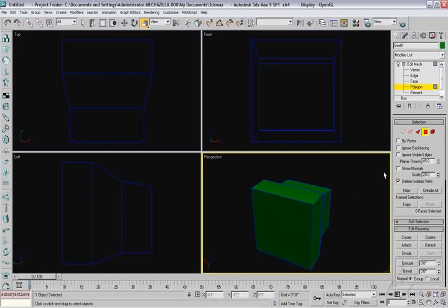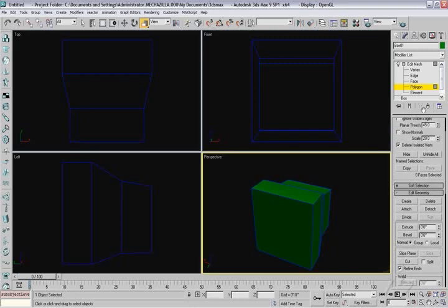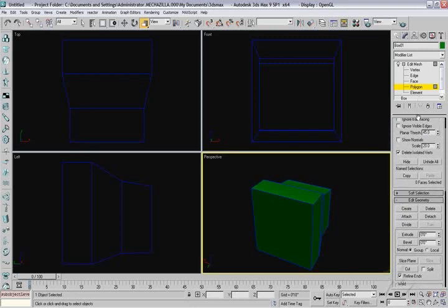Now we do that in the polygon mode. We've got some sub-object tools that we can use to work on this. Now 2 of the main tools that you're going to be using when you box model are bevel and extrude. During the last lesson you learned about extrusion of 2D shapes into a 3-dimensional object. We do this also at the sub-object level by grabbing a hold of things like the polygon and extruding it outward. So go ahead and click on your bevel tool.